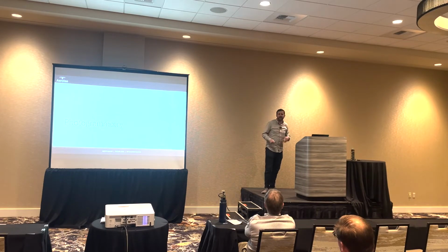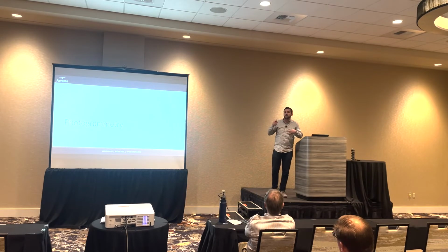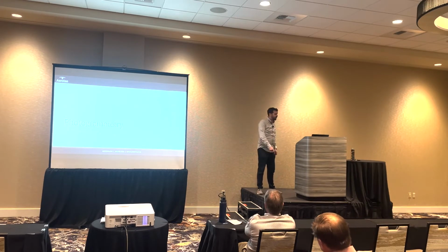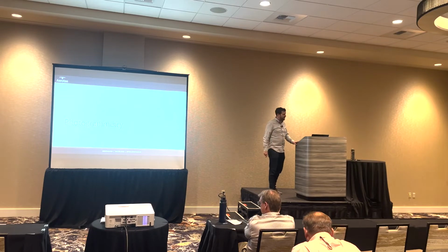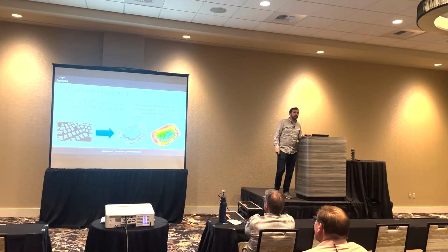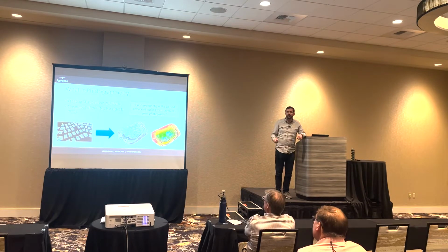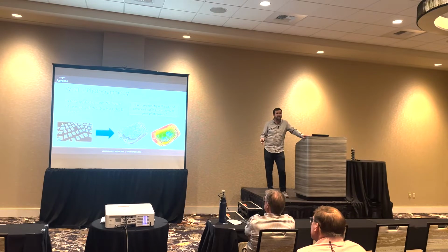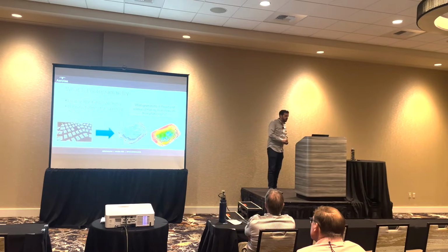That's the big caveat. LiDAR is much better in vegetation. It has the ability to penetrate vegetation and get you a good ground surface. With LiDAR, photogrammetry on hardscape is better. So that's why I really want to talk about photogrammetry. And again, that's the big thing, that LiDAR is not right for every project. Photogrammetry is better for many projects, and if you don't have a need for LiDAR, don't use it because it's a very complex and expensive workflow.